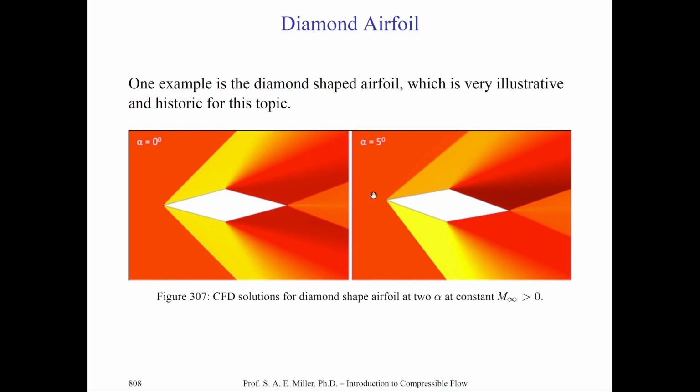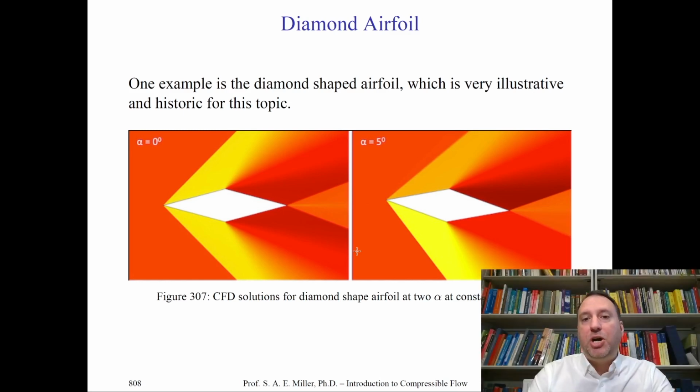This is, of course, because the flow going over the top of the airfoil, which is traditionally the suction side, has an oblique shock wave, which is having a different wave angle relative to the incoming flow direction. Why is that? Well, of course, indeed, it is because the flow turning angle is smaller than, of course, the flow going over the bottom of the vehicle.